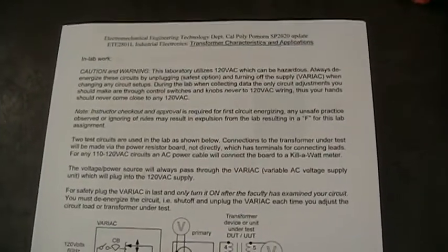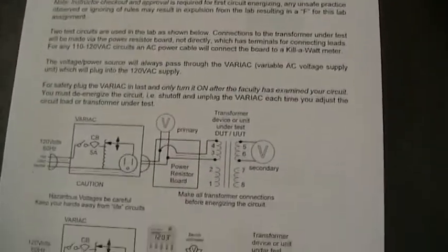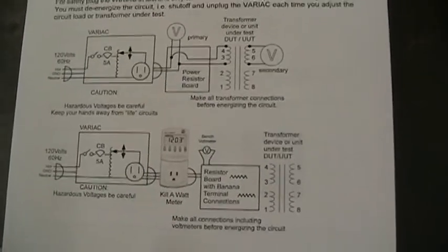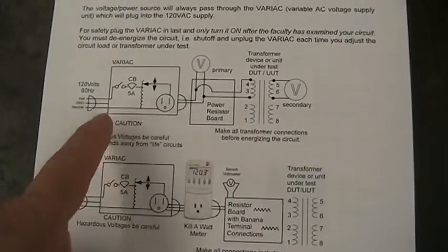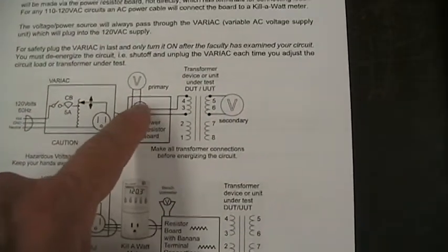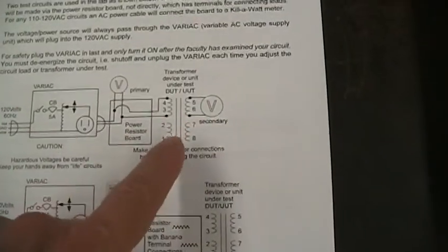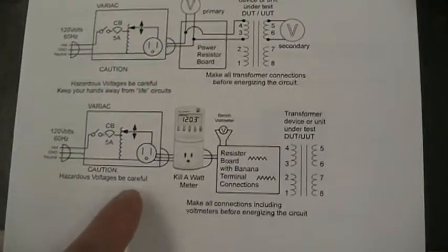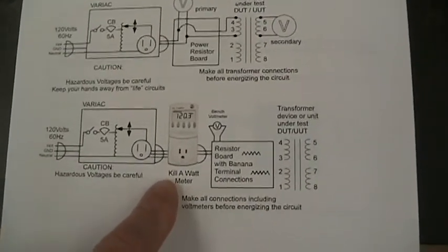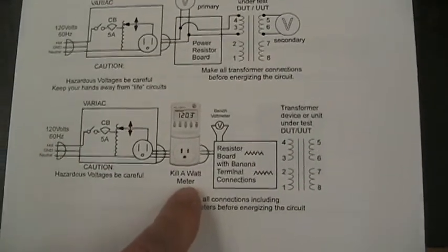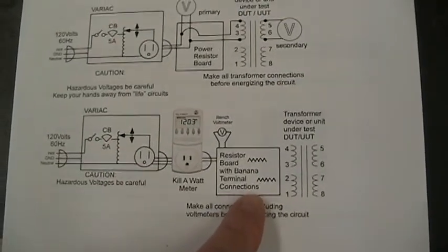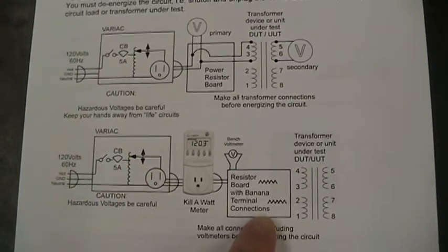Moving on to the active portion of the measurements, we'll be using 2 different circuits, mostly for instrumentation. When we're going to vary the input voltage with the variac, the unit we used in the AC Power Lab, we'll use a voltmeter on the bench to measure those voltages. When we have a fixed voltage, we know that the watts up meter, or the kilowatt meter, sorry, works well with the fixed voltage, and so we'll be using this circuit in the latter part of part 2 of the measurements.